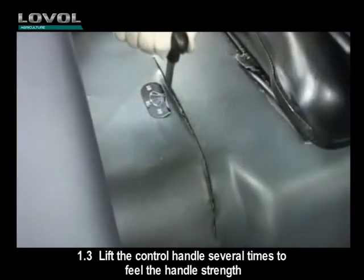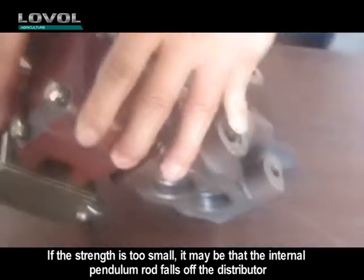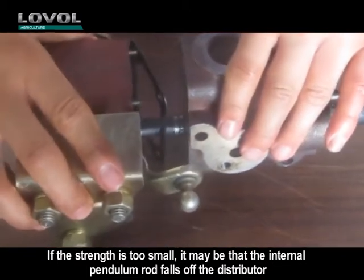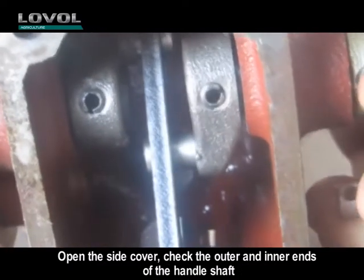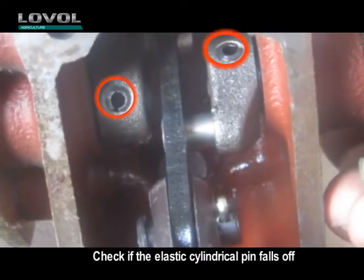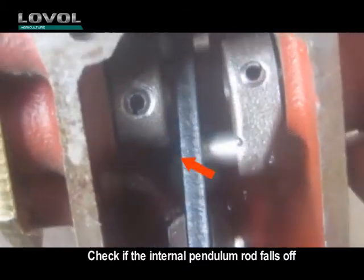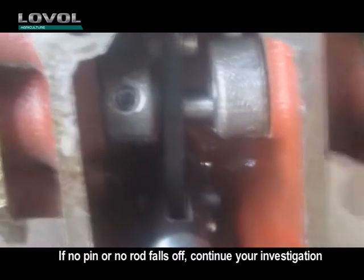1.3 Lift the control handle several times to feel the handle strength. If the strength is too small, it may be that the internal pendulum rod falls off the distributor. Open the side cover. Check the outer and inner ends of the handle shaft. Check if the elastic cylindrical pin falls off. Check if the internal pendulum rod falls off. If no pin or rod falls off, continue your investigation.